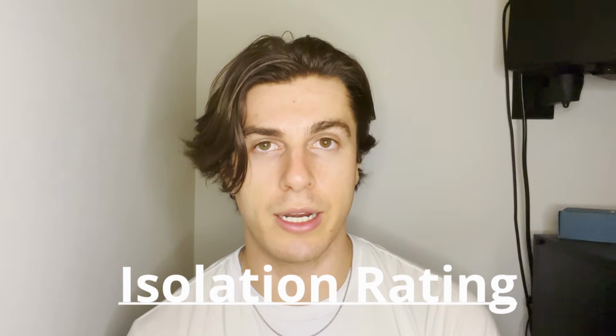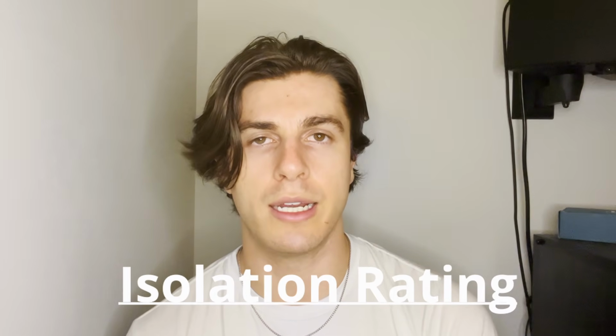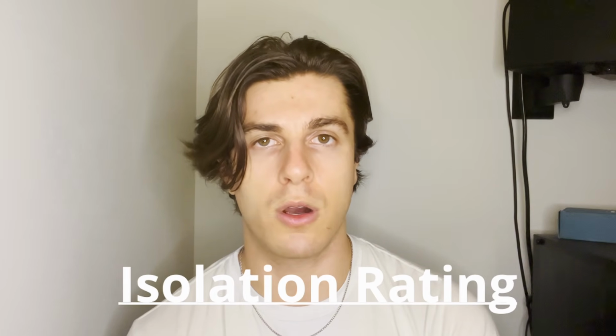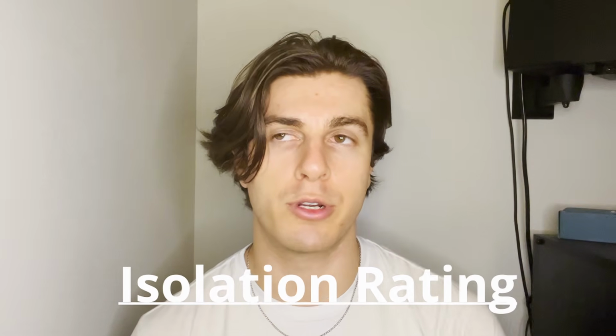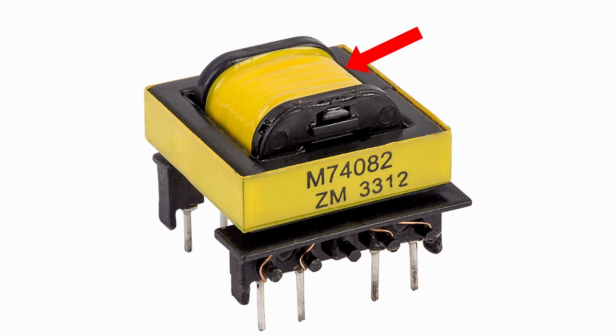And then there's another key parameter known as isolation rating, which is a measure of how insulated the transformer's windings are from each other electrically. A lot of times, if you open up the inside of a transformer, you'll see some insulative tape wrapped around the transformer. This is what is used to create the galvanic isolation between the primary and the secondary, so that they're not electrically touching, they're transmitting power wirelessly. One important thing to note for flyback transformers is that their design is oftentimes custom.